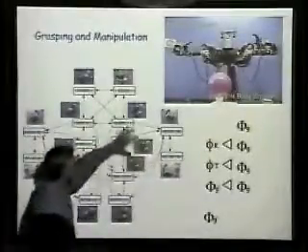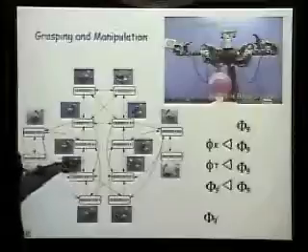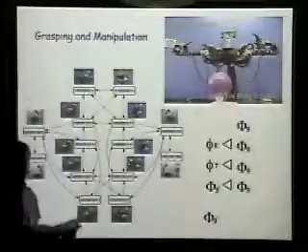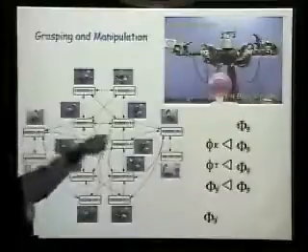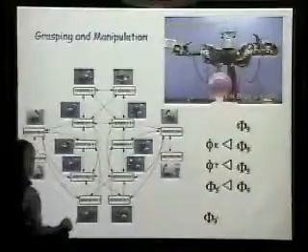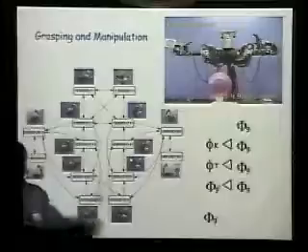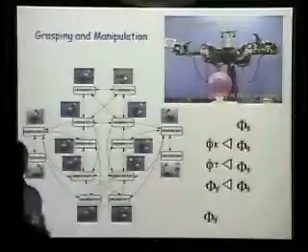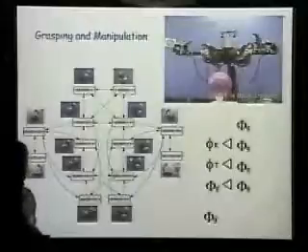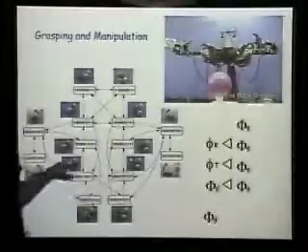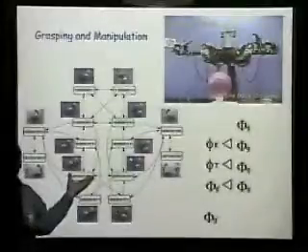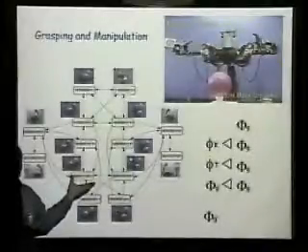It learns the topology of this graph. It learns every one of these arcs has a parameterized controller that affects that arc. And now it can migrate around in this space. So if you say, pick up that object, don't drop it, do some manipulation to it to assemble it into another object, or hand it to an astronaut that you're working with or something like that, but do not drop it. It has to find a path through this structure. This is a very structured space, and it can learn almost online like our walking platform did.